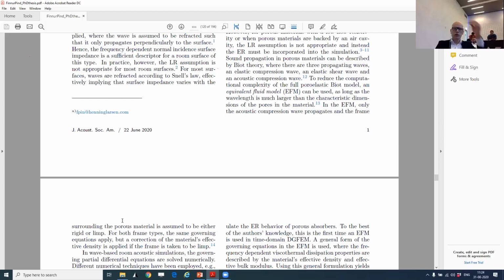You wrote, and I think you also mentioned it in your presentation, that the speed of sound in porous materials is smaller, so we don't have this time stepping problem, I think. Yeah. But the elements also need to be smaller because the wavelengths are much smaller. So does that scale in the same direction? So basically the question is whether the porous material determines the time step. There's some room for improvement here compared to the way we do it.